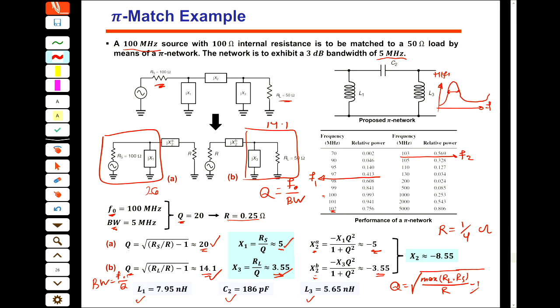Maybe we need to write down this based on j omega L and j omega C, and then see what happens in the denominator. For a single L and C, definitely it has one resonance because it goes somewhere high and then drops, or it is dropping, goes high and then almost constant. But for pi or T, maybe we have two resonances.